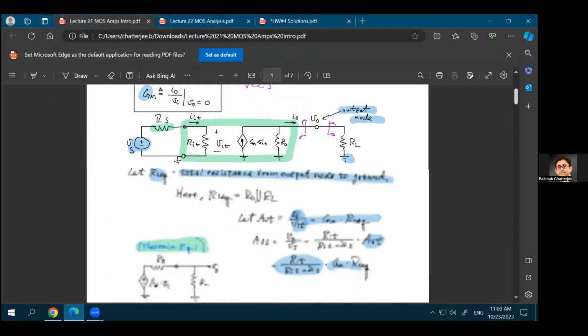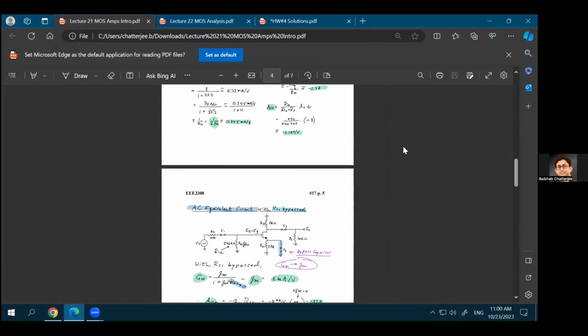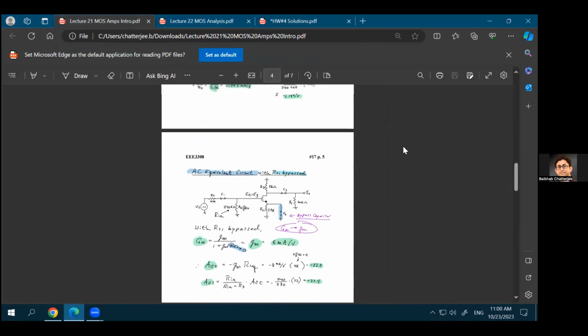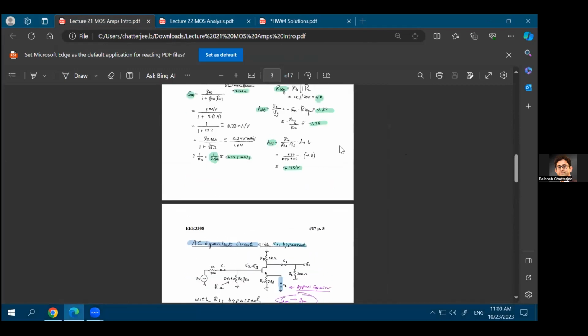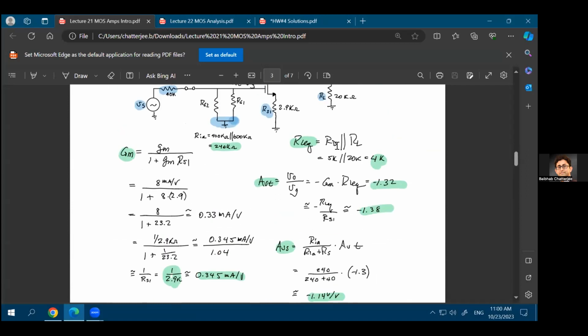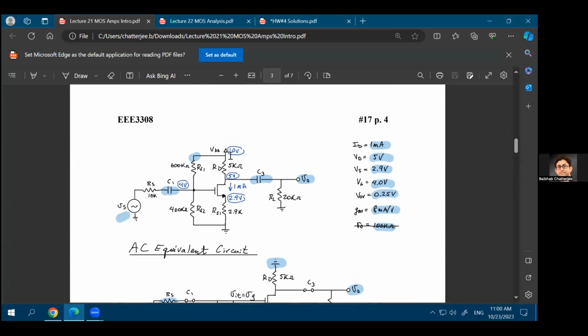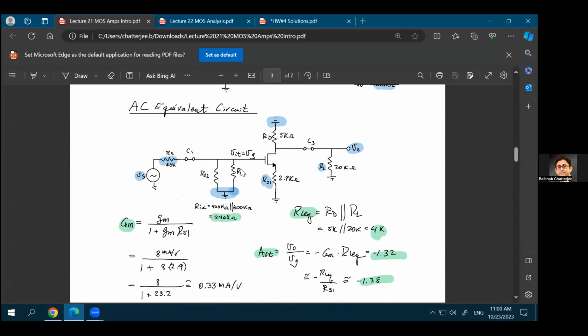All right, if not, let's go back to our AC analysis that we have been doing in the last few lectures. So this is where we were at during the last lecture, that for this circuit, which is very similar to your homework number 4, problem number 3, in terms of the DC analysis, you have these RG1 and RG2 resistances, you have RD as well as RS, and you are applying an AC voltage through this AC coupling capacitance over here. And we already solved this circuit.